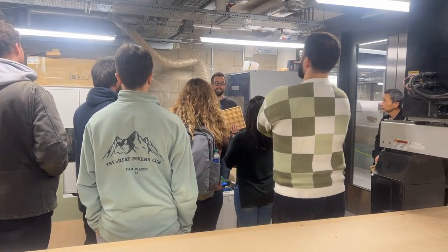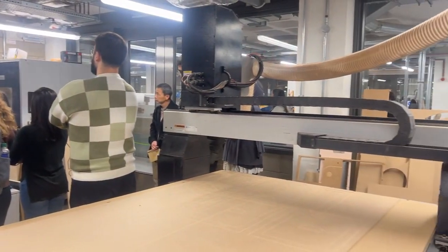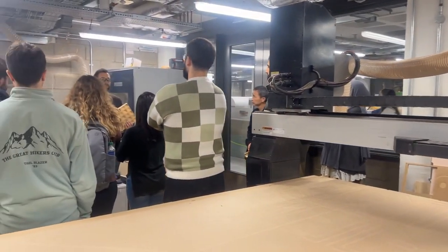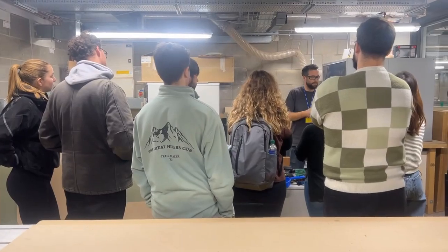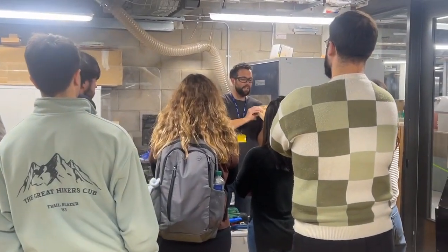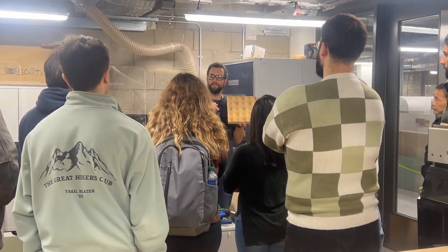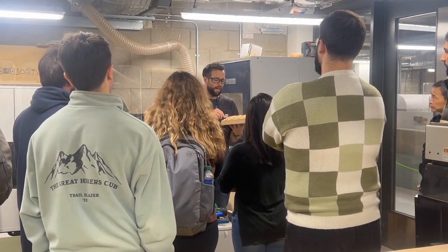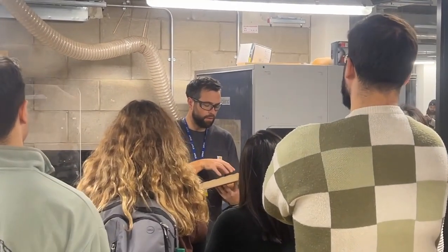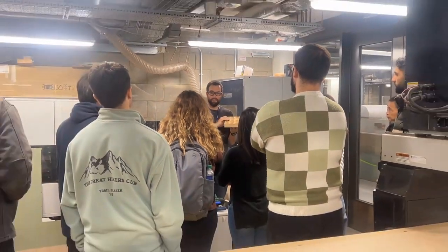There are 2 types of CNC cutting that we offer here. 3D shaping, which is what I believe you're going to concentrate on. Now, 3D shaping requires the cutter to move over a 3-dimensional model. Okay? So that's going to involve a 3-dimensional file showing all the different points in space.